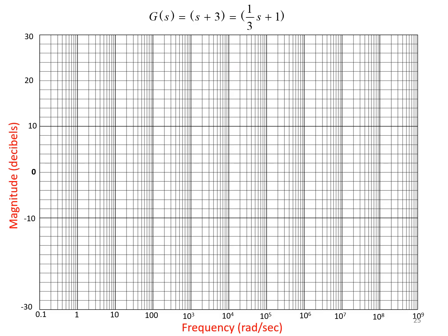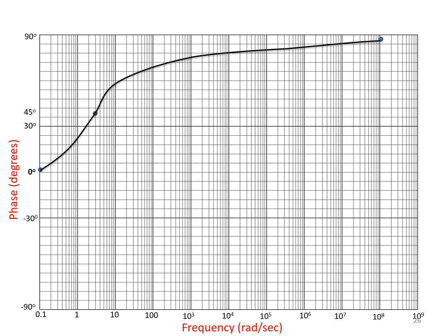Now let's see how we can represent them using the semilog graph sheet. Now this is about your plot. For a factor like this, we have the slope as plus 20 decibels per decade. And the phase value here is taken as 0 degree, 45 degree and 90 degree, and you will vary your frequency and join like this. So this is how the phase plot you're going to get for a factor.